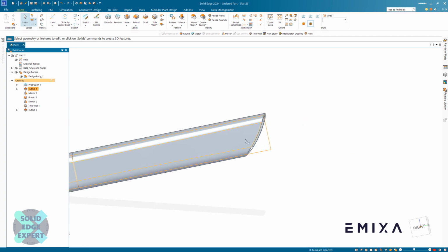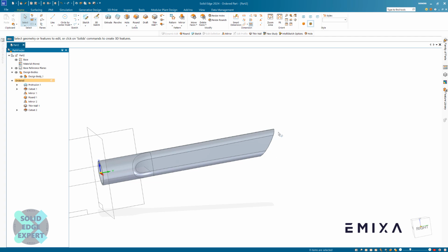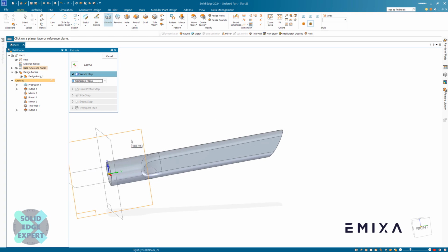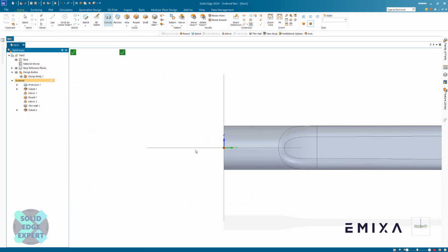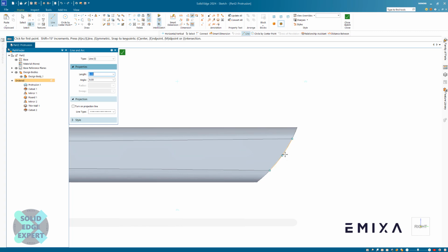Next, we want a little slot, a little kind of air hole, so we don't end up with a suction issue. We've got a curve which stops it, but it's quite nice if we have that on there as well. So for this, we're going to choose extrude again, and choose this right plane that we've been using before. Let's zoom out and zoom in and back out and go towards the end. I want a line starting from the end point, going in here.